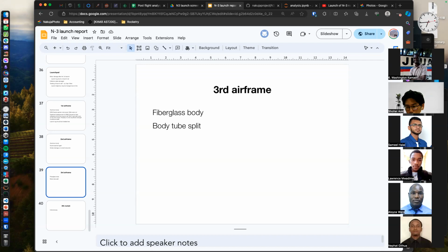Then additionally, regarding the failures we witnessed in the ignition system and all that, I may recommend that we design the system with a redundant mode, which would allow for a primary and a secondary circuit, allowing a quick changeover in case of failure of one of the lines.